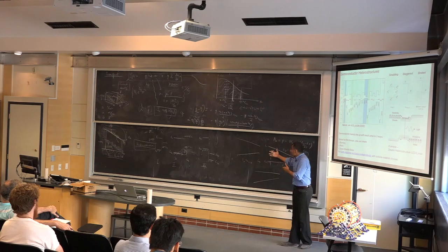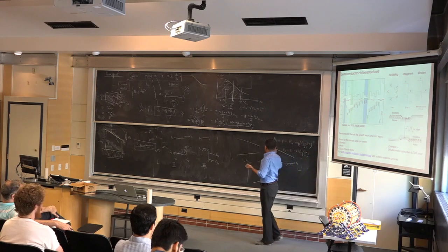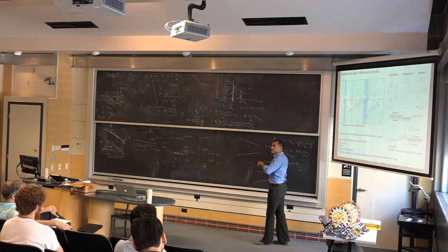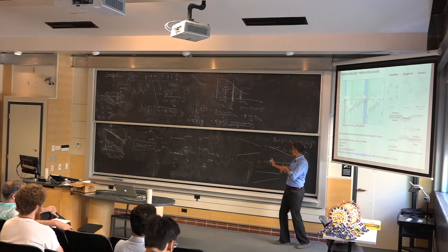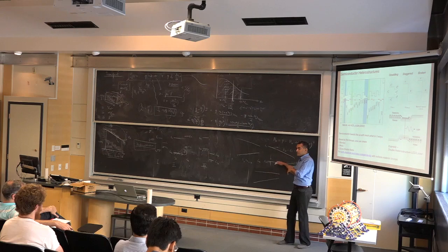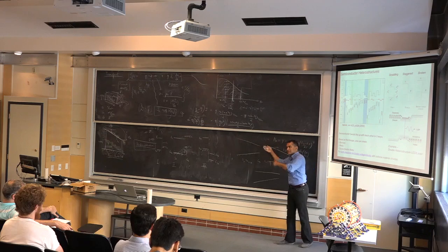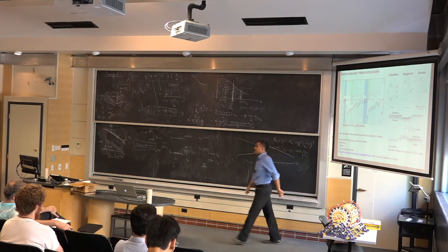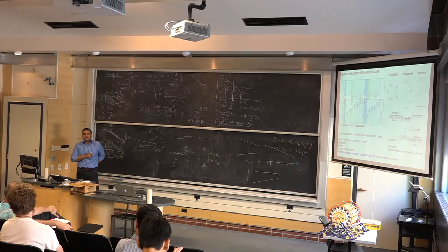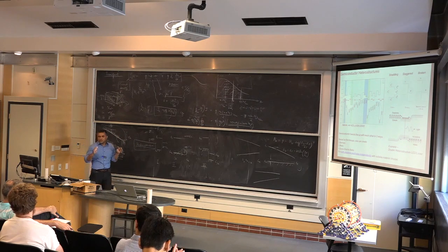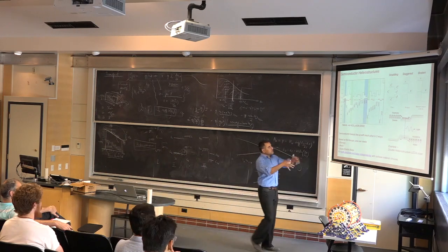Okay, so that is because of the heterostructure. This is exactly the essence of what we call a quasi-electric field. This is not an external voltage. This is built into the material because you change from silicon to silicon germanium, and you doped it p-type. The combination of these two has given birth to a built-in electric field in the material. So doing a heterostructure is, in a certain sense, similar to putting two metal electrodes in a structure, and so I can do a lot more fun things.